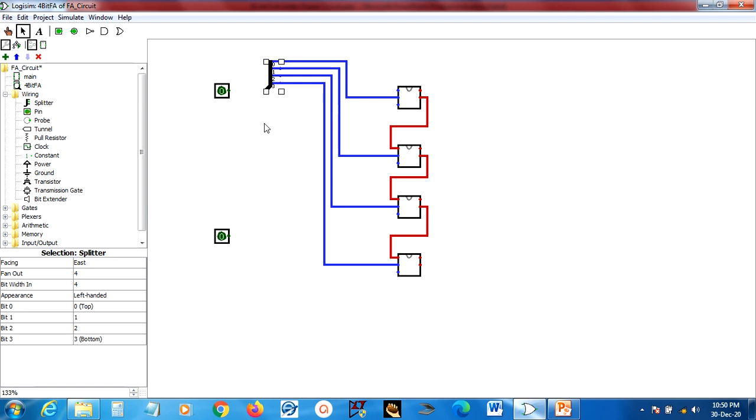Alright. So now let us connect here. It says incompatible widths. So we have used a splitter which is 4 bits in length, but the input is only 1 bit in length. So select here and make data bits equal to 4. Right, again we will label here, it is A4. Let me call it A4 to represent 4 bits. Right, let us make it bold.